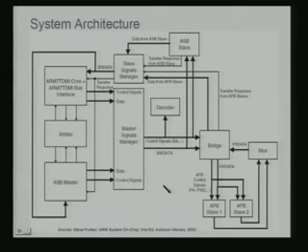So this is the basic architecture of an SoC using the two buses, that is a hierarchical bus structure, and all data transfers here are in parallel. They are both parallel buses, and this system bus, which can be ASB or AHB, is capable of handling a variety of complex transactions, and these give more flexibility and speed to the bus.